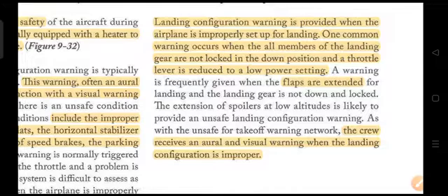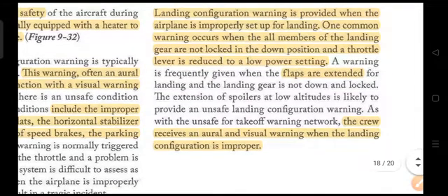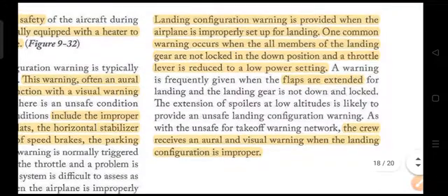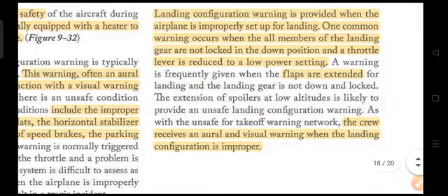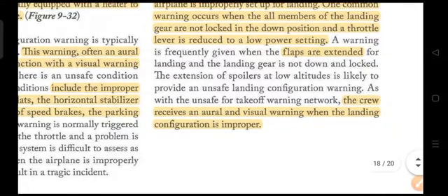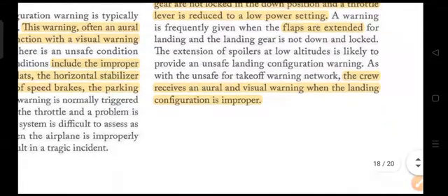of putting down the landing gears and locking them, because it understands that maybe the pilot has not focused on putting the landing gear down before slowing down. So it considers that the aircraft is landing without the landing gears down. That is the reason it always informs the pilot that you have to put the landing gear down the moment you decrease your speed with the throttle.